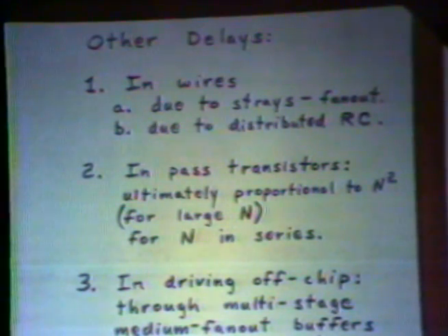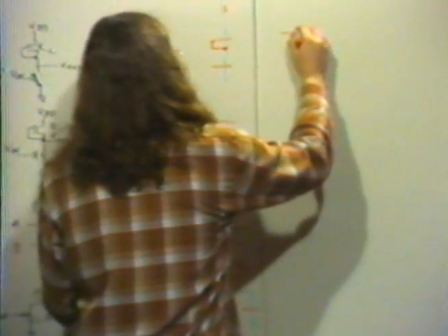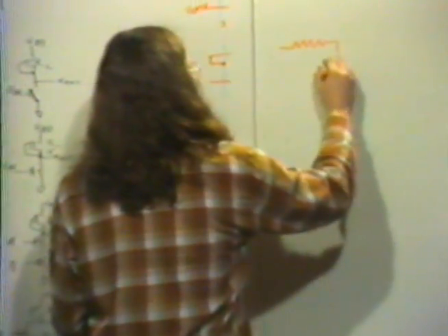So in two of the three layers, there's potential for quite a bit of delay in a signal propagating down these wires. Let me just draw a schematic. I'll give you a lumped approximation to what that distributed resistance and capacitance looks like. It consists of a series resistor, a shunt capacitor, repeated many times for each epsilon length of wire.